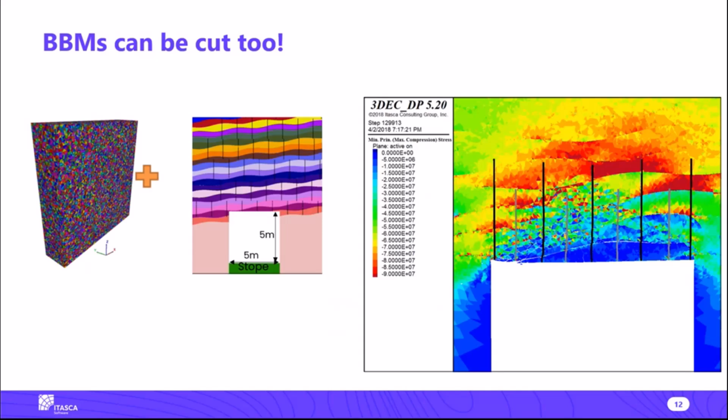And then you can take this to another level. So imagine you have a shape and you fill it up with tetrahedra, like I'm showing on the left-hand side here. You can then cut a second layer of joints on top of that. So you have your background joints in between all the tetrahedra, and then you have the more large-scale joints cut through that.